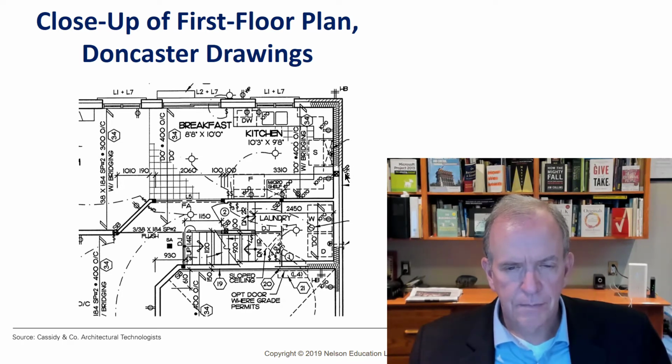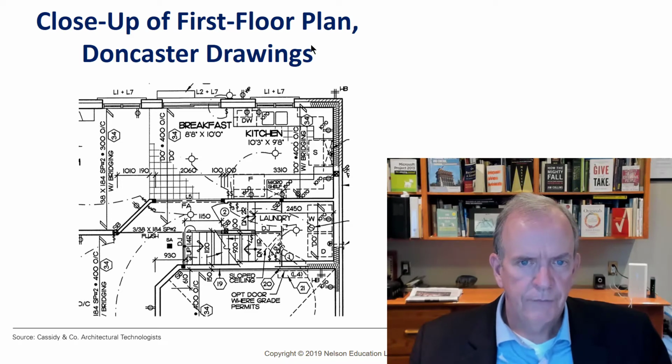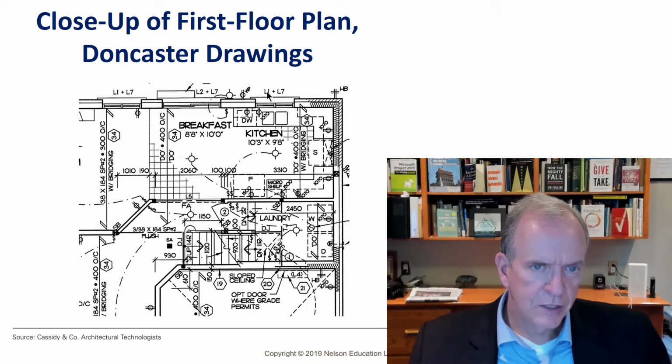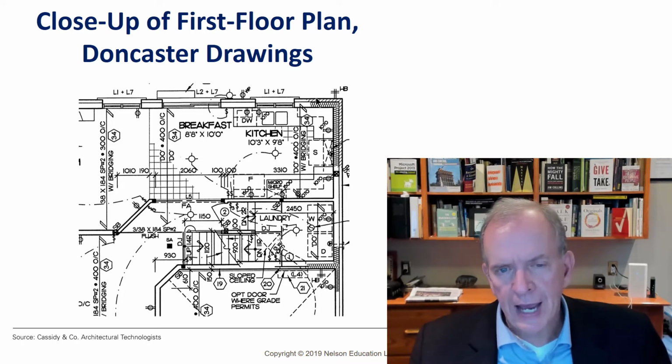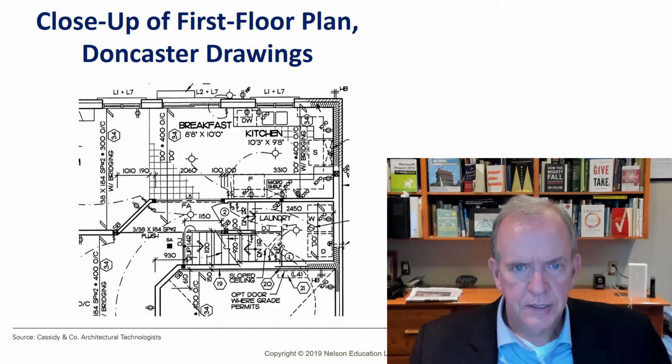This is that solid bearing that I was talking about, SB, which is coming down, which is supporting the roof truss from up above. This is for a hose bib for your hose. This is the lintel sizes that we were talking about, L1, L7. L1 would be for the wood lintel. That's part of the wood frame structure. L7 would be for the steel lintel for the brickwork. This is a hatching indicating brickwork. This is a hatching indicating insulation, batt insulation inside a wall.